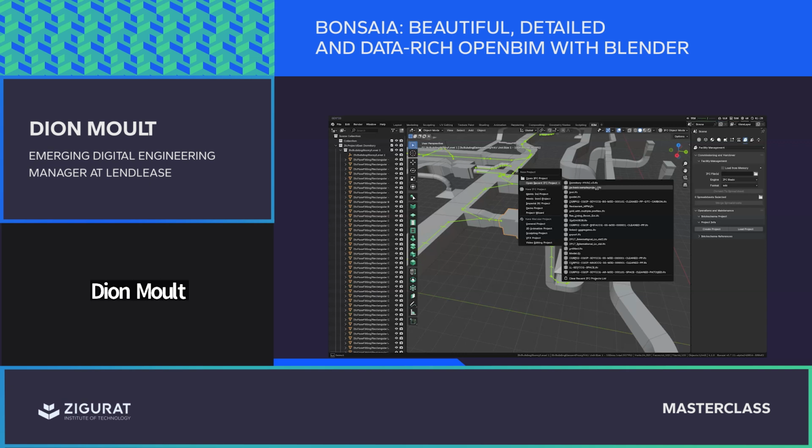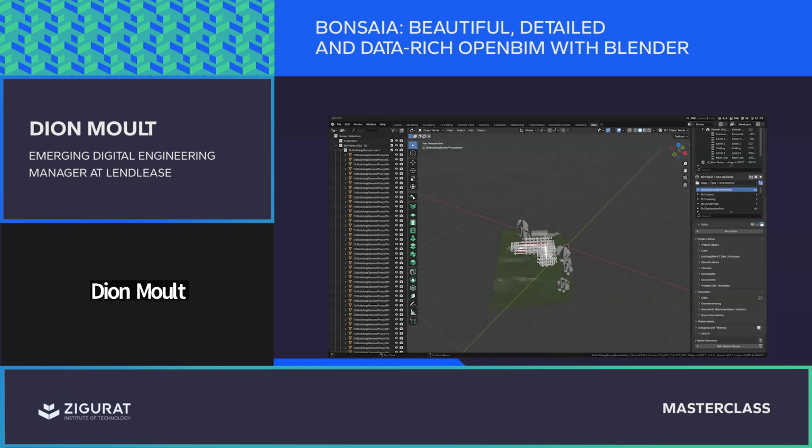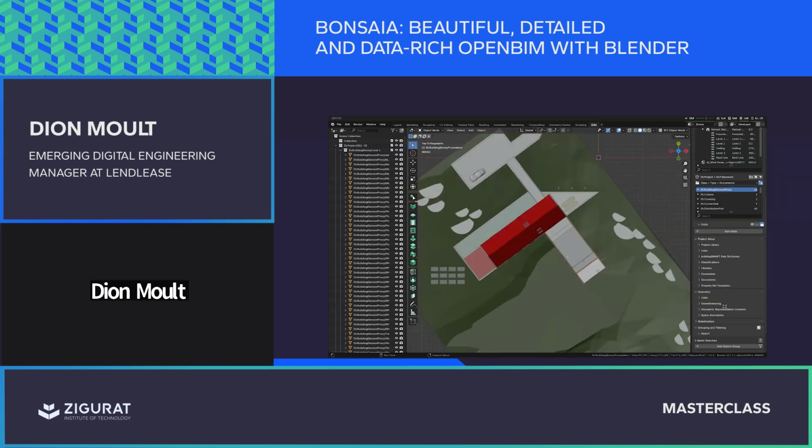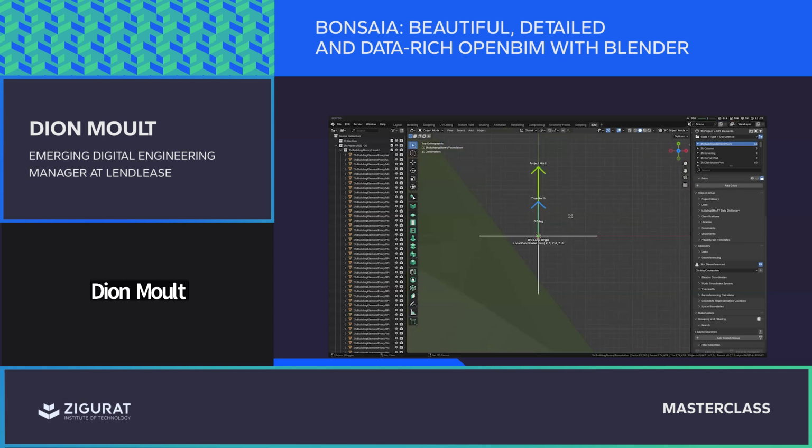So let's jump back to this model over here. Turn off those grids again. They are quite in the way. Let's do a quick check on georeferencing. You can see that this project is not georeferenced. This is actually quite a fun fact. I would say that a good 90% of BIM models are not correctly georeferenced. And people who think they have georeferenced their models have not.